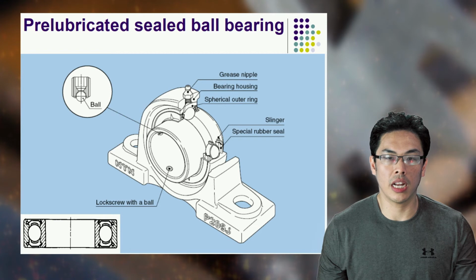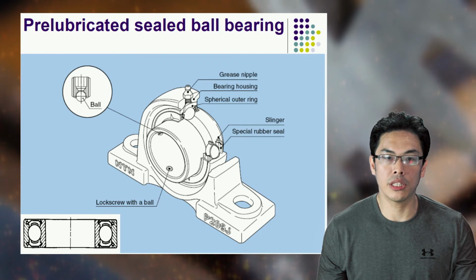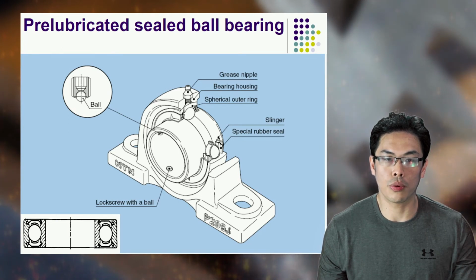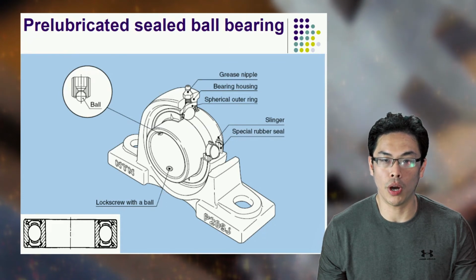Oil is generally used to lubricate rolling bearings when high speeds or operating temperatures preclude the use of grease. Excessive heat has to be removed from the bearing position. Adjacent components are lubricated with oil.